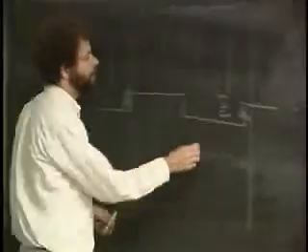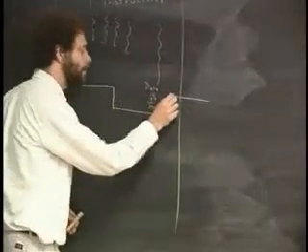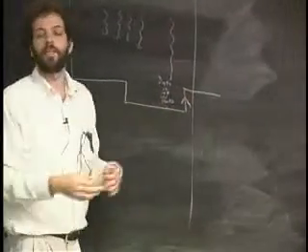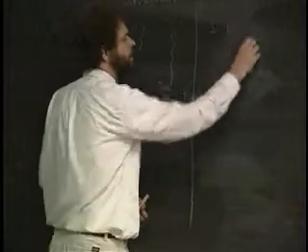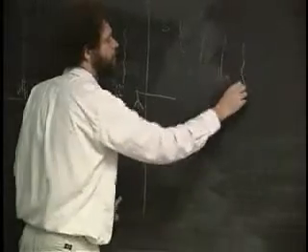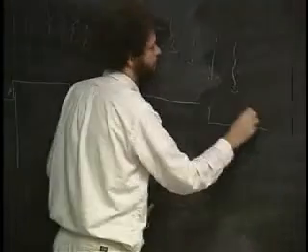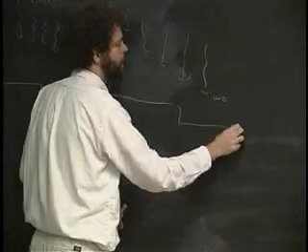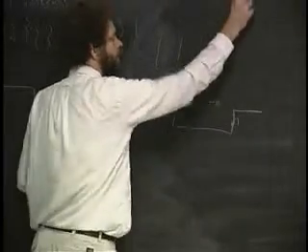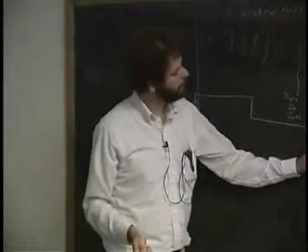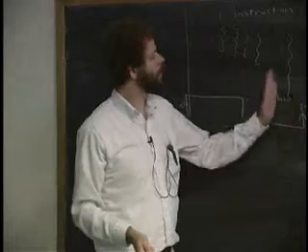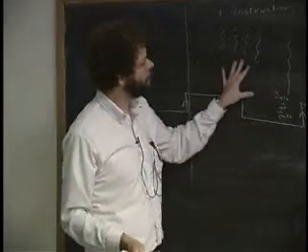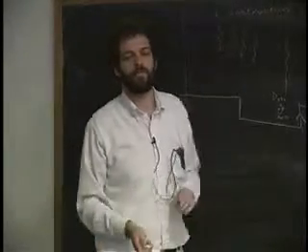And then the clock goes off, and that marks the end of the instruction and sort of the beginning of the next one. And then the next one starts, and again we get the percolation of data down and down and down. And then finally that ends with everything waiting at WD, and then another clock, and we begin with the next opcode. So you can think of these edges, and I've drawn the next one starting here just a little bit, but you can actually think of it being on that line, where this marks the separation of one instruction and the next one that happens. Okay.